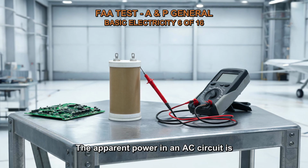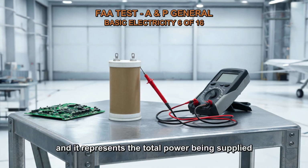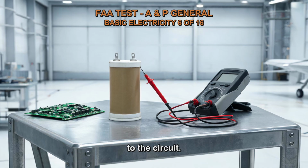The apparent power in an AC circuit is the product of the voltage and the current, and it represents the total power being supplied to the circuit. However, the true power, also known as real power, is the portion of the apparent power that is actually doing useful work. In a reactive or inductive AC circuit, the true power is less than the apparent power because some of the power is being consumed by the reactive components and is not doing any useful work.